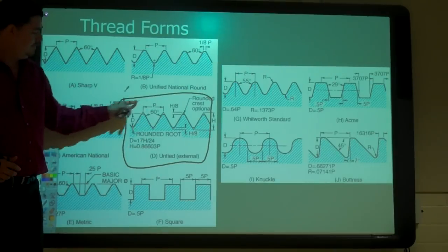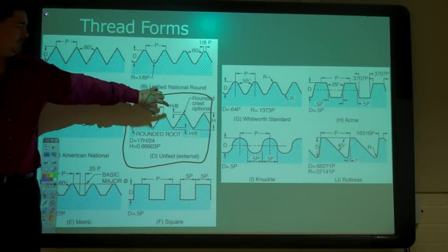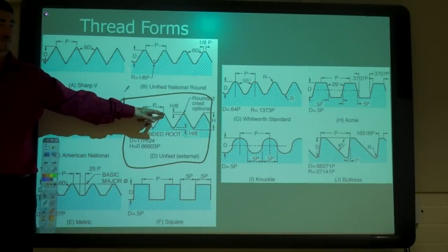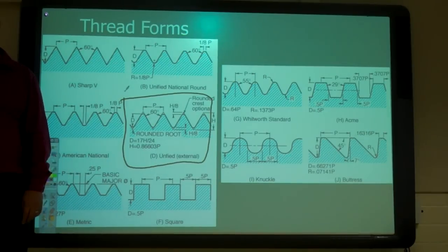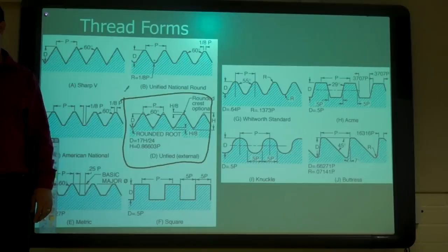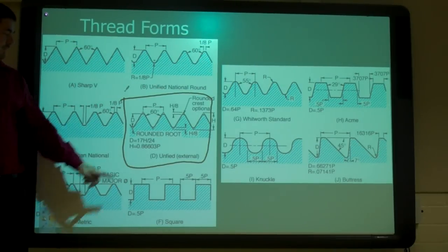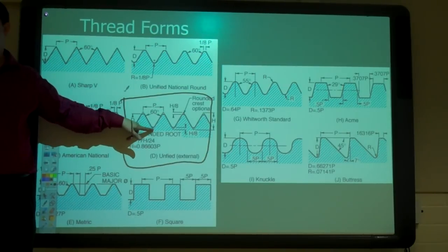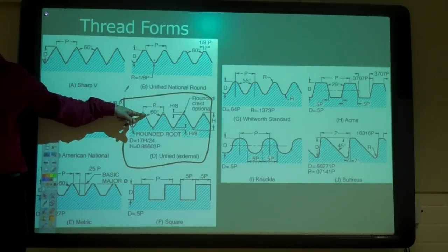6 degrees between them, and then the pitch. And we kind of cut off the tip. Why do we cut off the tip of it? Because that's an external corner. Why do we need extra space? What do we do down here? Down here is not sharp anymore, so up here can't be sharp.